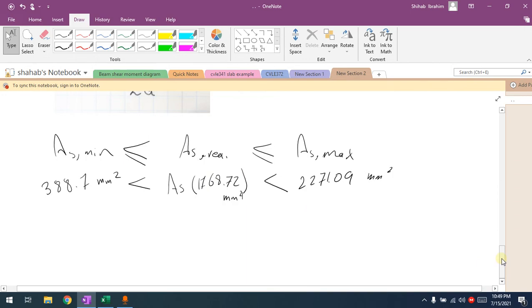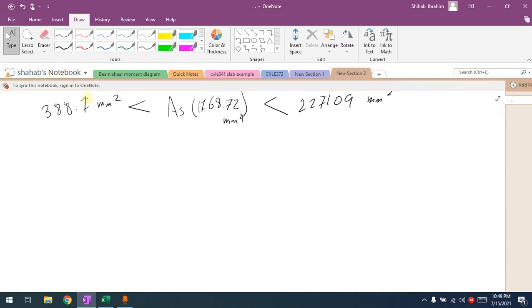Now I can do the checking. Yes, I have AS, I can find a, same approach. We have to check now, yes? So we have to check basically for what? Check to see if what we started all of this with, Fs equal to Fy, holds here. Some books say to use this AS and do analysis directly to see what will happen. Now if the analysis does not pass, then you will come back and change something from the design.